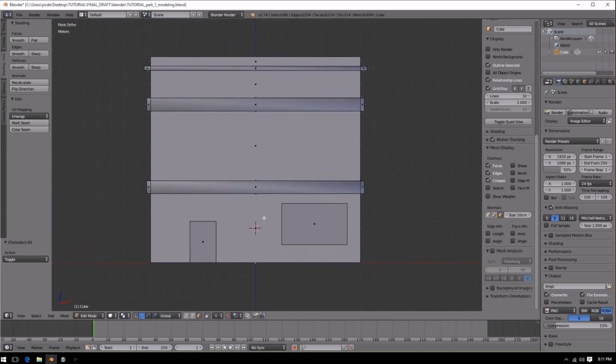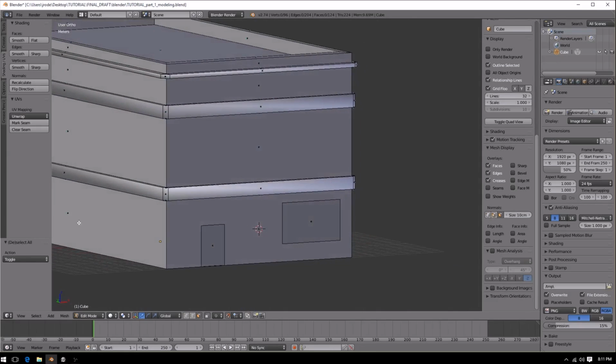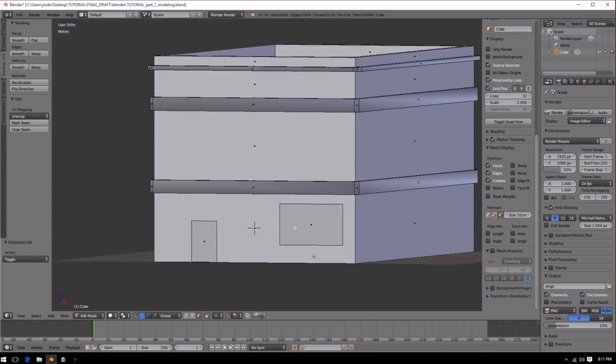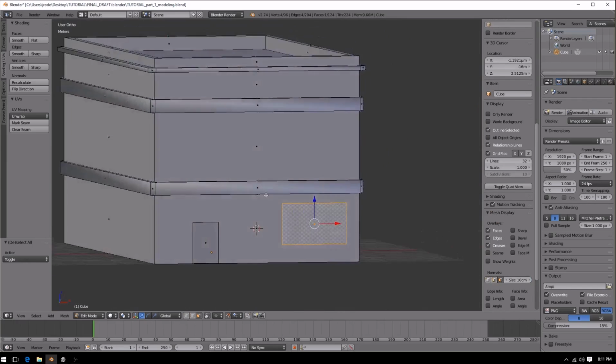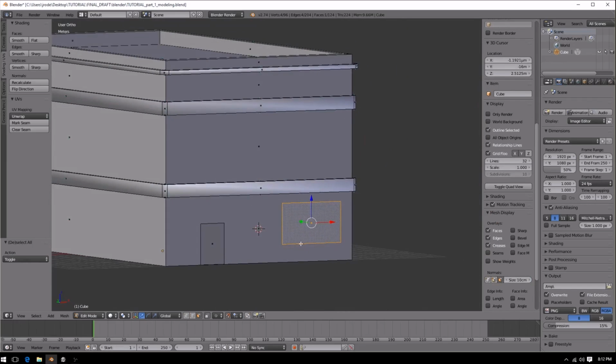Alright. So the next thing I want to do is make the same thing for this plane for a garage door. Eventually I'm going to use the same plane and duplicate this and make windows up on the 2nd floor and maybe even this floor. But in order to make this UV unwrapping easy, I'm just going to make one of them right now. Any unique piece of this building, make one of. And then when I have to UV unwrap it, I only have to UV unwrap it once.